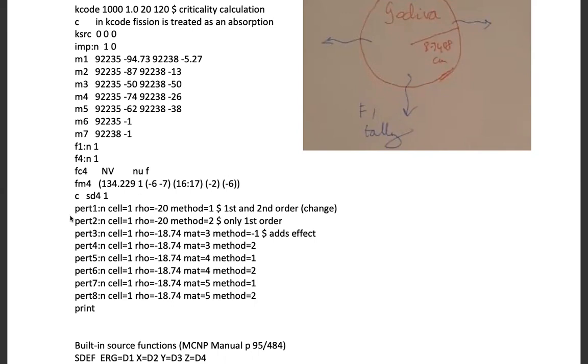Okay, now this is the perturbation option that I've got. So I can do a sampling. MCNP carries out sampling for the derivatives and for correlated. It estimates from the correlated simulation and from the derivative sampling from a single simulation. It estimates the first and second derivatives. So as you can see, the PERT card, you can put any number with it, but it slows it down. So the PERT 1 for neutrons.